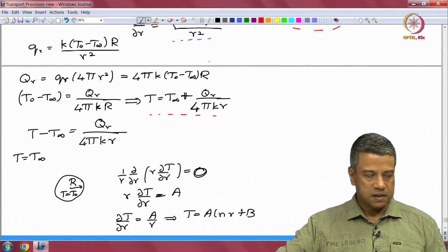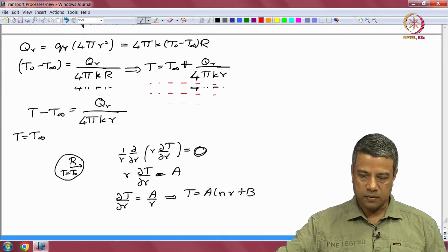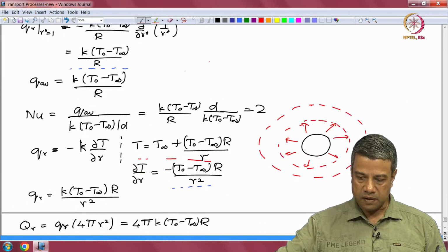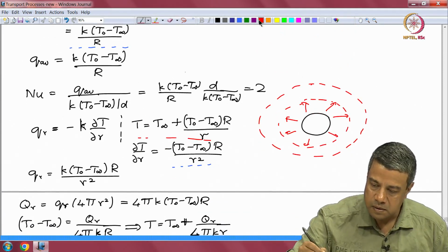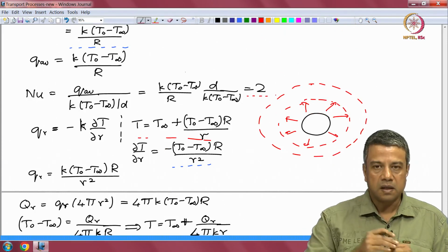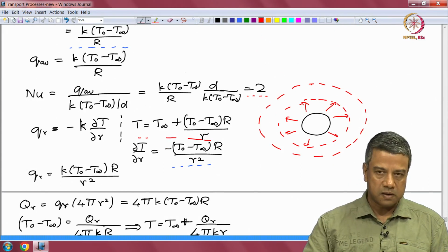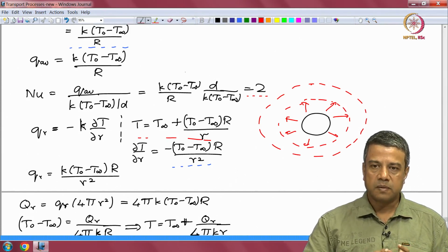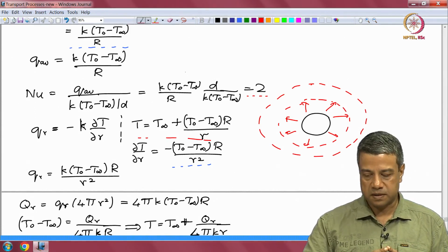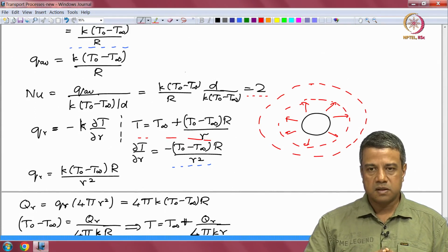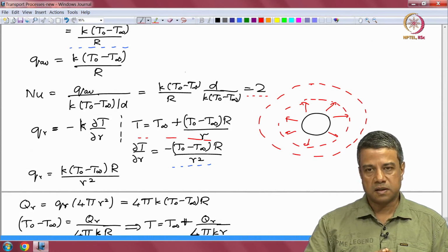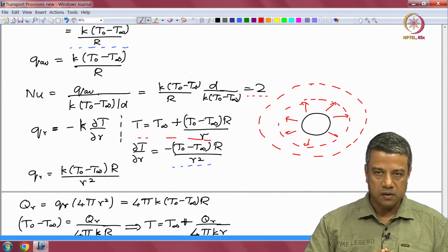And we had solved the mass diffusion and the heat conduction equation in order to get the Nusselt number correlation for a spherical particle, which we had used earlier. This correlation which we had used earlier has been derived here. The procedure is what we will usually use to derive correlations. Solve for the fields, the temperature, the velocity or the concentration fields over the entire domain.